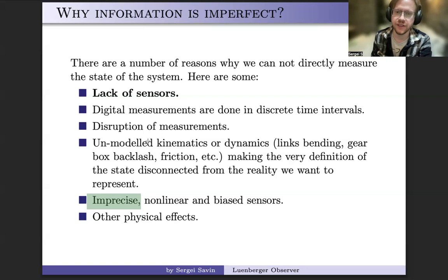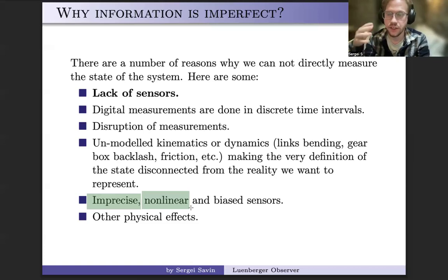They naturally produce errors. Sometimes sensors are non-linear, so they would behave linearly on a certain range of measurements, but then they would have a non-linear part of their range. And sometimes the sensors are linear as long as temperature is correct. But change temperature significantly, and they will start to behave slightly differently. All kinds of things happen. So while it is possible to control for all of this, in some cases you have to deal with those kinds of things. And they can be biased.